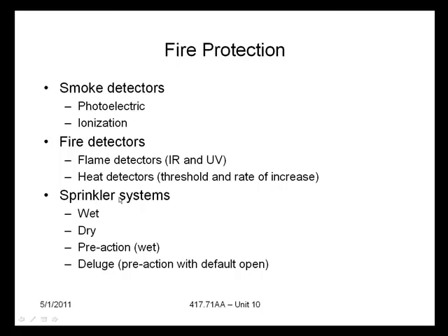These detect smoke, not so much fire, but it's important for human safety to protect against smoke because most deaths are caused by smoke inhalation. You don't actually fry to a crisp in a fire. You end up suffocating or inhaling noxious gases from the smoke, and that causes most fatalities in the event of a building fire. Fire detectors include flame detectors, both for the infrared, the heat nature of fire, as well as ultraviolet rays, which are emitted by certain types of fire. These are factors that distinguish fire from natural light and from artificial lights that light up most work areas.